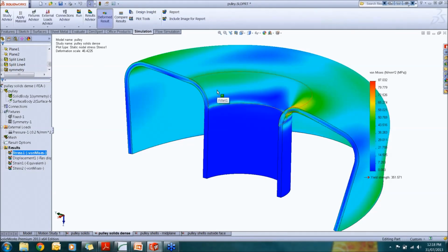So in that very simple model, what we showed is that from an initial estimation of 2 seconds to a more accurate result, or let's say a more realistic result, we are increasing our time by a factor of 10. Just imagine if you have a very complex shape or a very complex assembly, and getting the right mesh alignment and orders could take a very, very considerable time if we are still with solid elements.